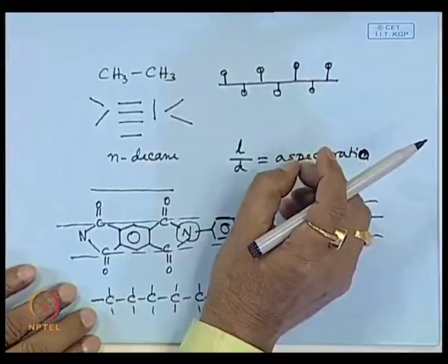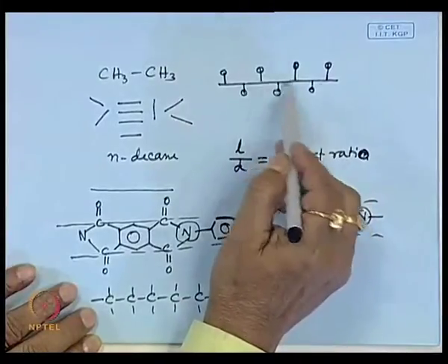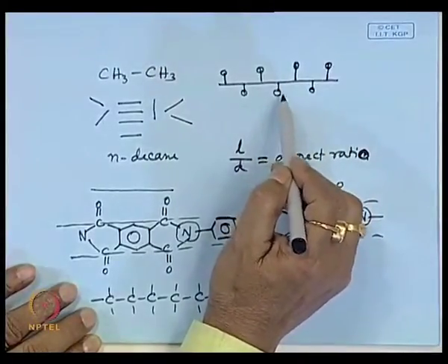Say you think of linear polypropylene polymer, where the methyl group can make its configuration isotactic or syndiotactic or atactic. Atactic is the random configuration which is amorphous in nature, a soft weak polymer, whereas isotactic and syndiotactic have regular symmetry or regularity in the molecular configuration, that means in the substituent pendant methyl group.